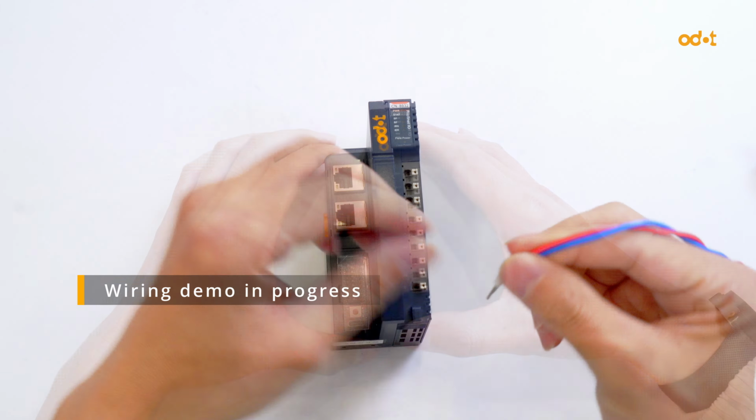Next, click to add a new device. Expand the list and find our 1214 DC. Choose the corresponding PLC based on the order number. Then, click OK. And that's it. The project is set up.